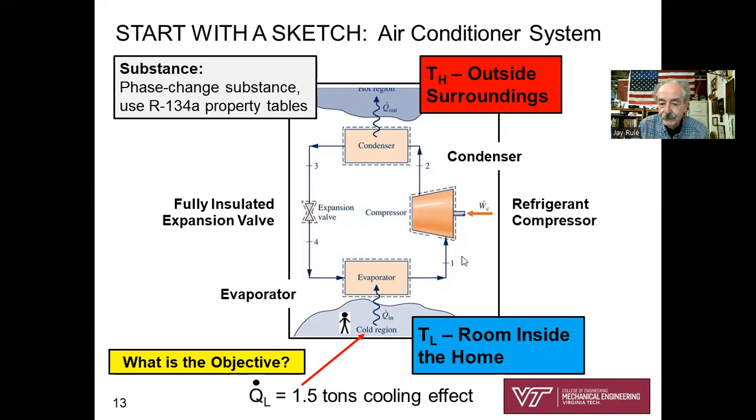Let's see, it said going in is saturated vapor. State 2 leaving the compressor going into the condenser. State 3 leaving the condenser. It's going to be a saturated liquid. The condenser is where we reject heat to the surroundings. Very hot condenser refrigerant, very hot. Okay. 3 to 4 is the expansion valve process where the pressure drops and the refrigerant gets very, very cold.